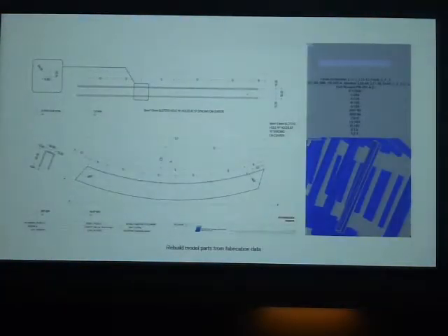And we also needed to make sure that the fabrication documents we were creating would actually result in the correct parts. So therefore we created Grasshopper scripts to interpret the information that we created from these models and use that information to recreate the parts in 3D and compare them to the parts that we modeled to make sure that everything would actually lead to the correct piece. So here you can see that we actually compare that recreated part against the model.